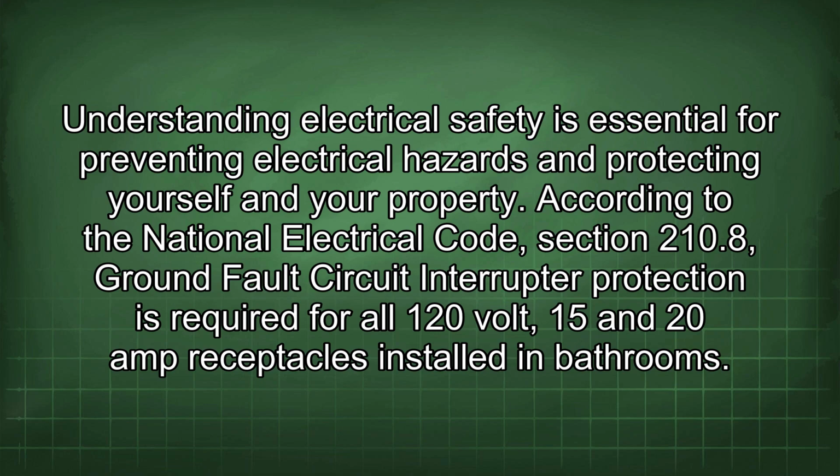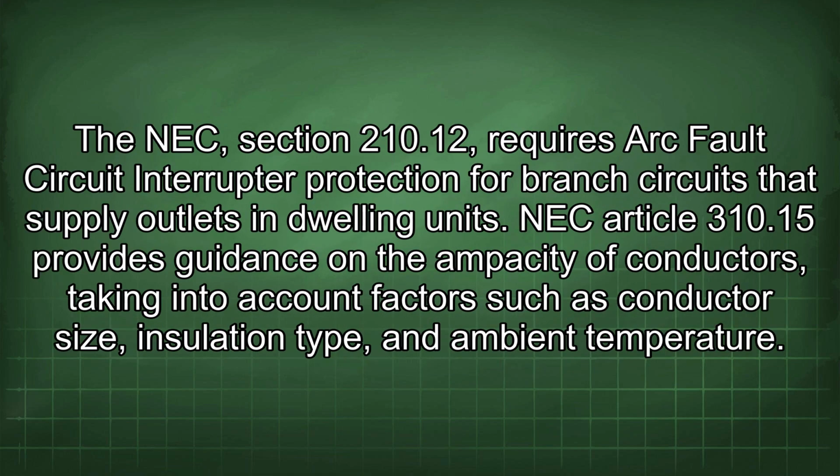According to the National Electrical Code, Section 210.8, ground fault circuit interrupter protection is required for all 120-volt, 15 and 20 amp receptacles installed in bathrooms. The NEC, Section 210.12, requires arc fault circuit interrupter protection for branch circuits that supply outlets and dwelling units.